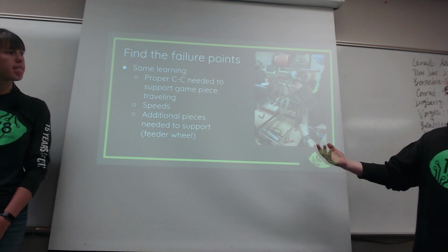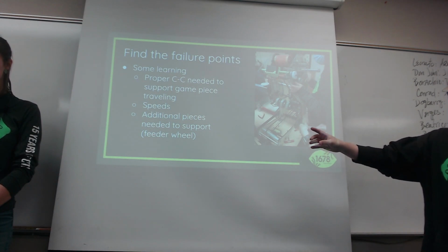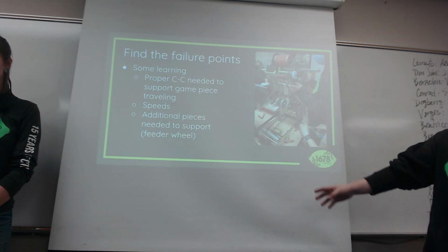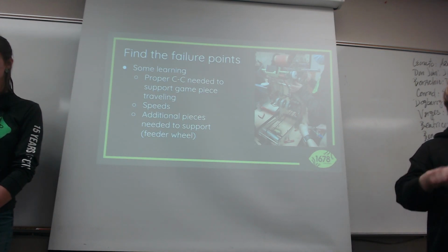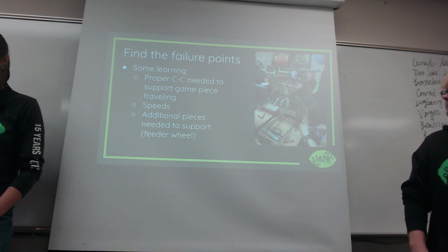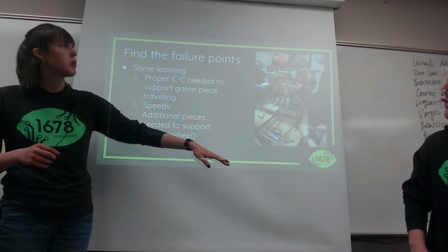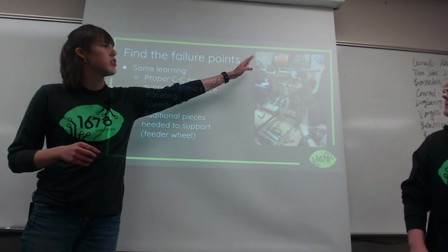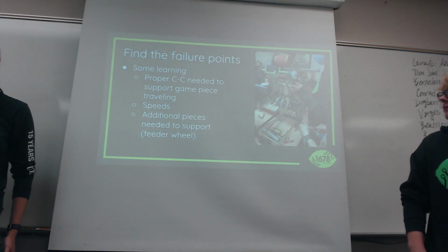And then an example of what happened here when we found out something didn't work was we realized that in order for this to function as something that brings up, you would want a feeder wheel because otherwise there's nothing actually driving it up enough because the two little loops of polycord was not cutting it. Yeah. So at this point, I believe these are two different prototype groups. Someone was working on the shooter and someone was working on the hopper, and we just put them on top of each other to see how it would work together.